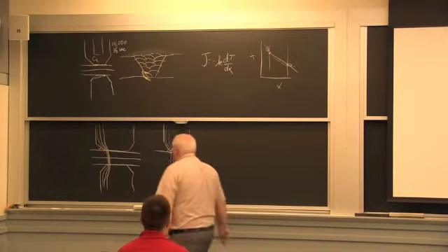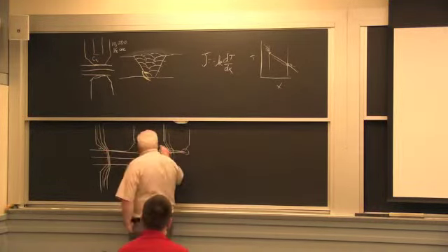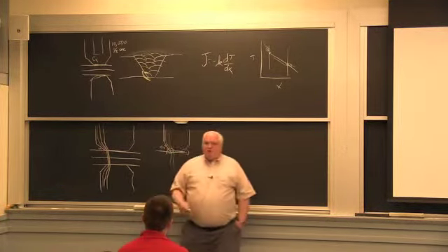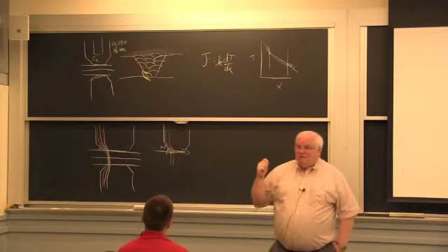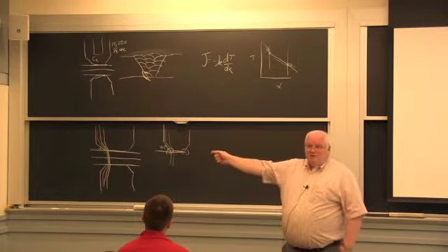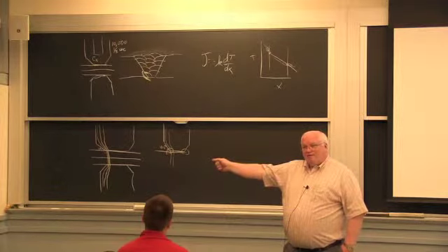What were they using in the plant? A 15-degree angle. What were they using to run the test? It was actually part of the Ford spec, 45 degrees. Okay, 45 gave you a better electrode life. But then you go in the plant and you use the one that gives you a lousy electrode life.